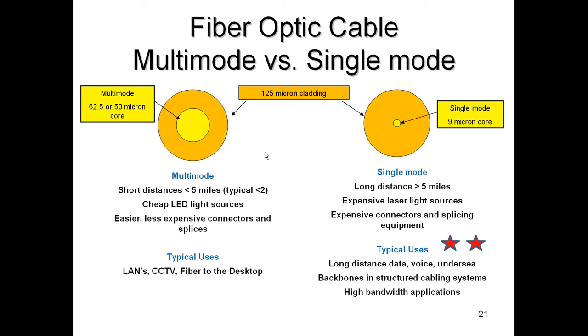So do you see that when we're transmitting data, and by the way, we can transmit analog or digital or Ethernet over either kind of fiber. But when we're transmitting, whatever the kind of data it is, if our light can turn on and off faster, do you see that it can transmit more? So single mode, because it uses lasers, gives us higher bandwidth. In fact, where the bandwidth of a multi-mode fiber is about 48 times that of a typical Cat5e cable, the bandwidth of a single mode fiber they have yet to find the end of it. There is lots of bandwidth in a single mode fiber.